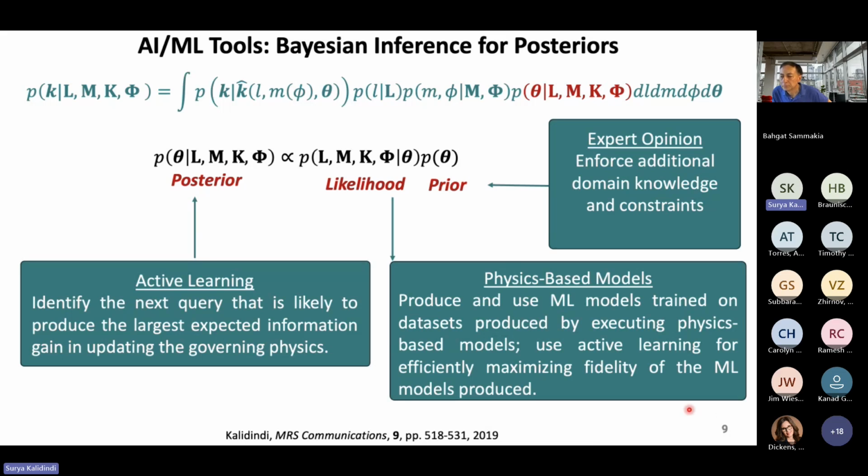Hopefully it'll get better. So the one other area that is hard is basically inference. For example, the term in red at the top is where you're matching the experiments and simulations. So one of the hard areas is how do you match experiments and simulations. Normally people would call it model calibration, and in the simplest and most common case, the approach is a deterministic matching.